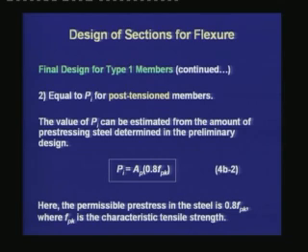For a post-tension member, we can neglect any loss due to elastic shortening if there is a simultaneous stretching of all the tendons. Even if the tendons are stretched sequentially, the elastic shortening can be neglected at this point, and hence we can equate P0 to Pi, which is the force measured by the gauges of the jacks during the prestressing operation.